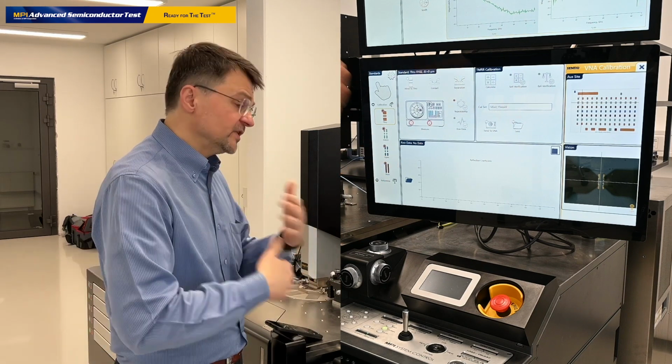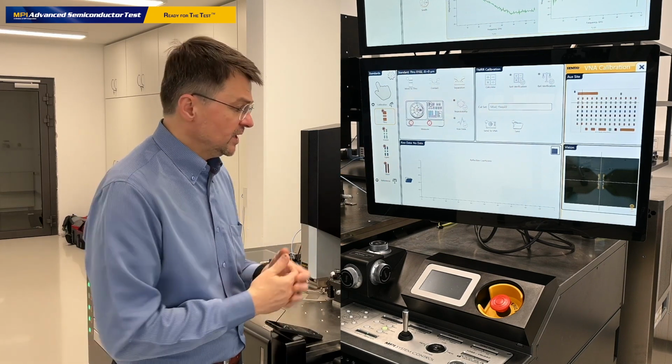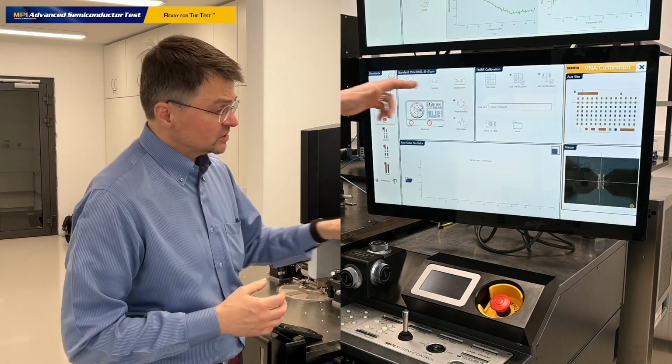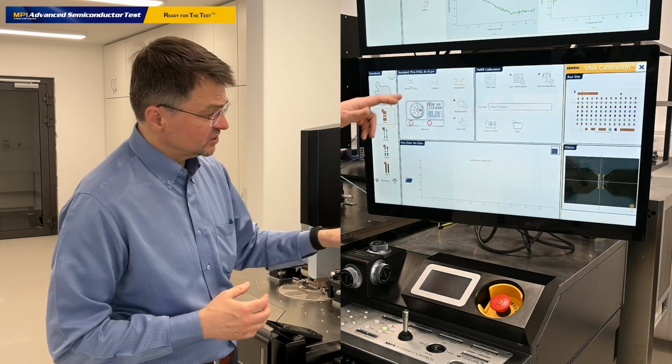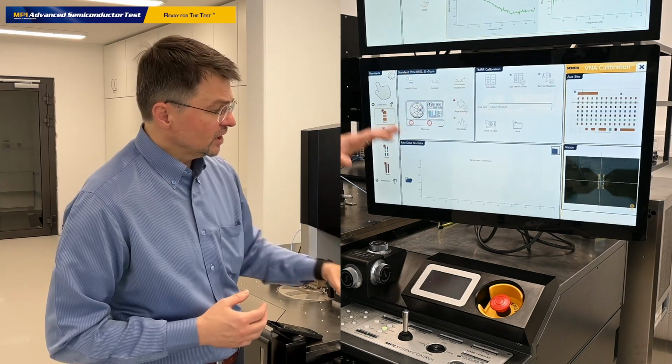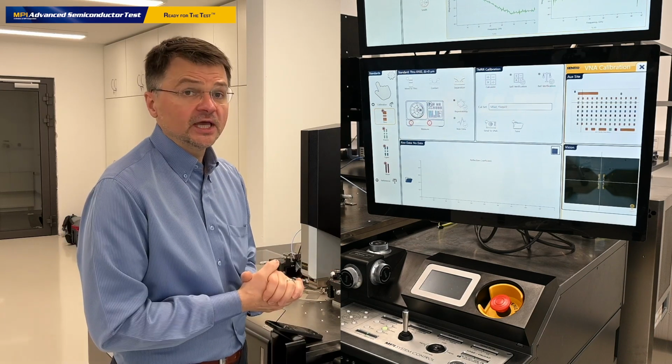If we go over the calibration measurements in the manual mode, it means that we move to every individual calibration standard manually, so we can navigate to the selected calibration standard, like moving to the through, moving to the load, moving to the open, to the short, from this widget, and we can trigger the measurement procedure.